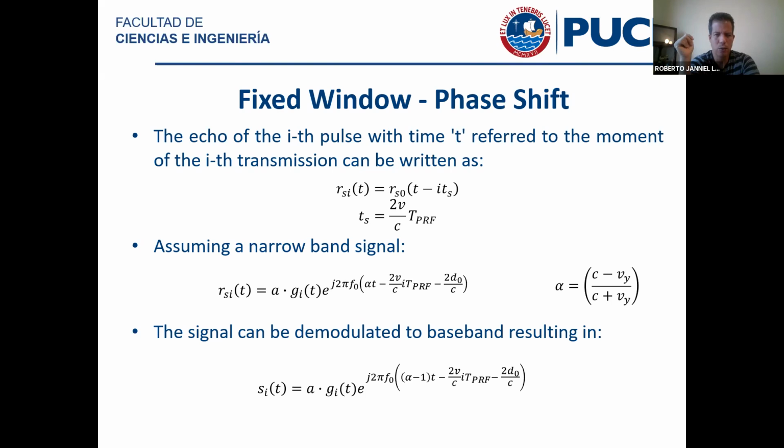And that's, parenthetically speaking, the reason why in Doppler imaging you are going to use long pulses, even if you operate in pulse wave mode. Now, long pulses doesn't mean that you're going to transmit 20 cycles of the fundamental signal, but it's roughly something like 6, 8 cycles. I mean, you still make it long, just so you know.